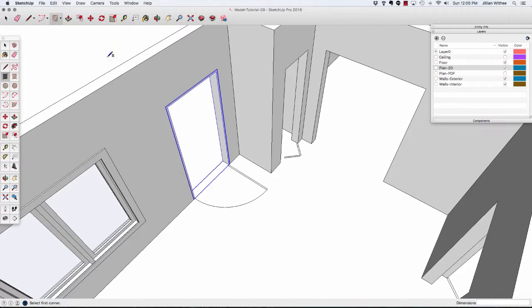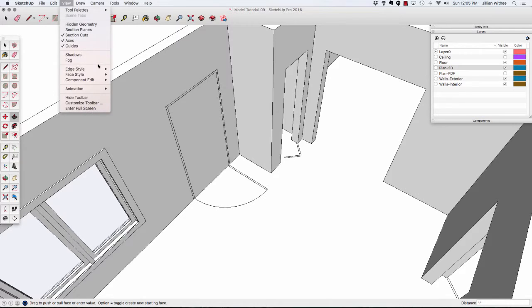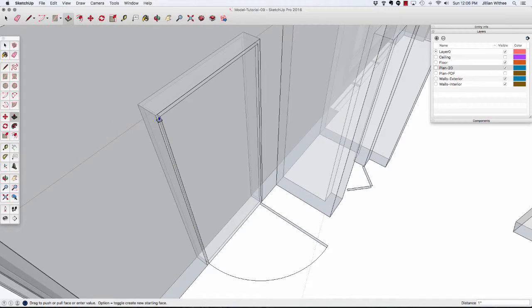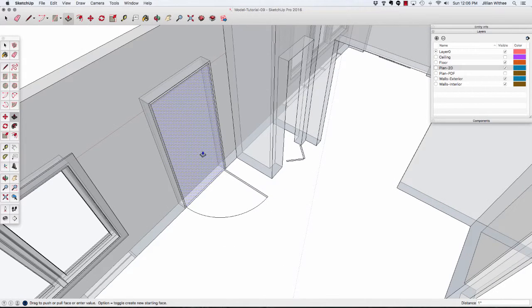Very simple. We'll click on our rectangle again, draw from corner to corner inside the frame this time. Then we're going to create a recessed panel door. So first we're going to click back, push that back 1 inch to extrude it. If you want to see that, you can turn on X-ray mode, and now you can see there's a thickness to that door panel back there.